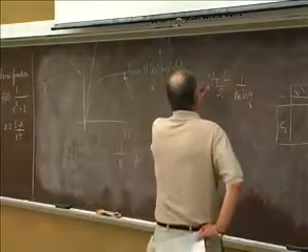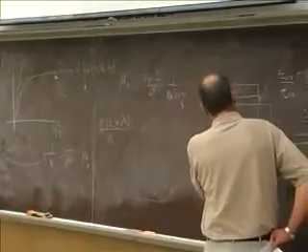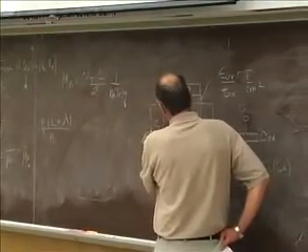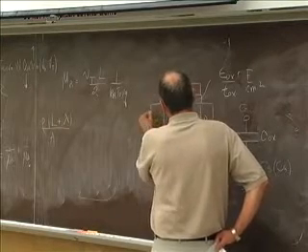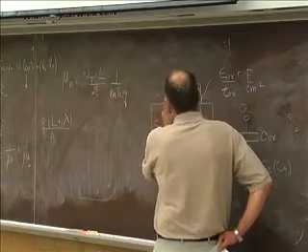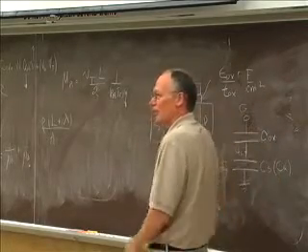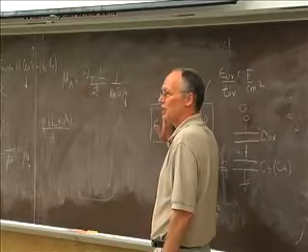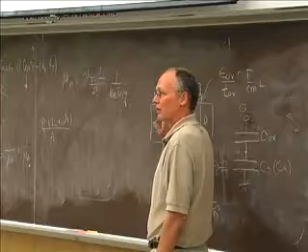Yeah. Make sure Cyprio agrees with this. What we're doing is electrons are coming in from the source, and we have this top of the barrier. We're populating these states with a Fermi level according to the band structure at the top of the barrier, which we're thinking of as the beginning of the channel. So it's the effective mass at the top of the barrier.